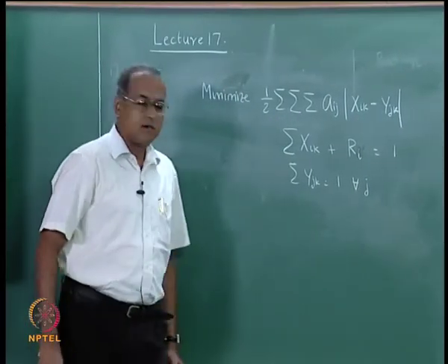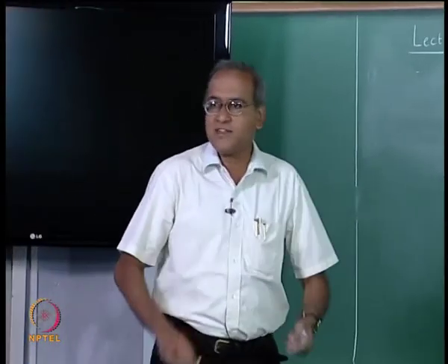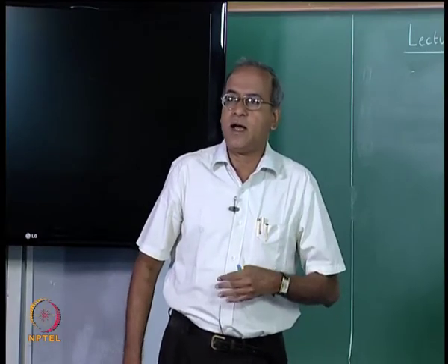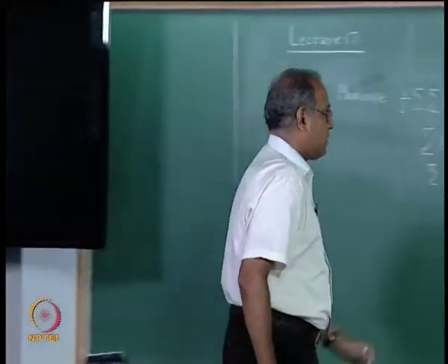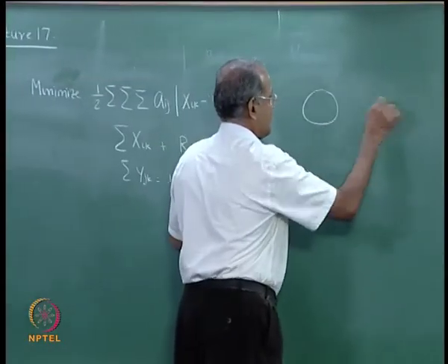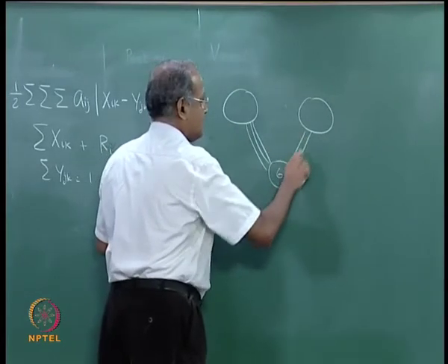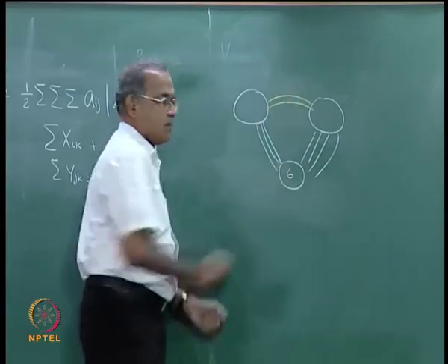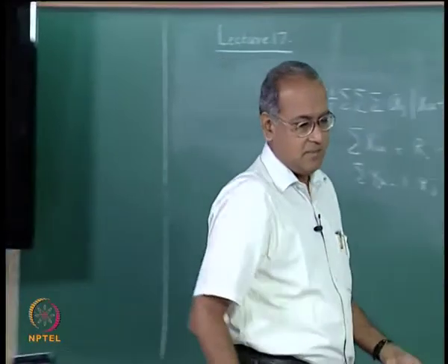r_i equal to 1. Next thing we have to ensure is that all the machines do not go into the remainder cell, because we are not going to add the intracell moves for the remainder cell. Again going back to the example, there is this, this and this, 6 was here, all these moves are not going to be added, only these moves are going to be added. So, we should not have a situation where all the machines go to the remainder cell.